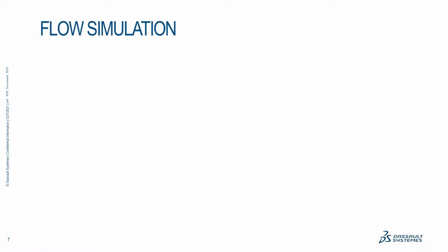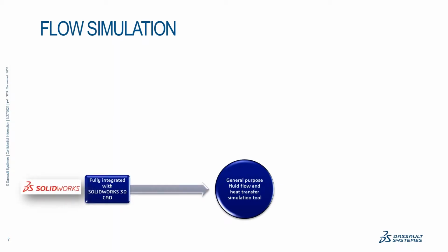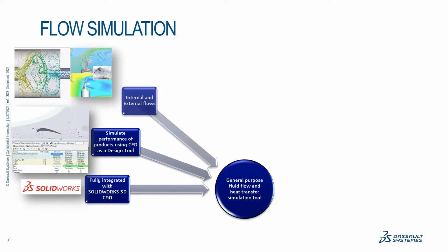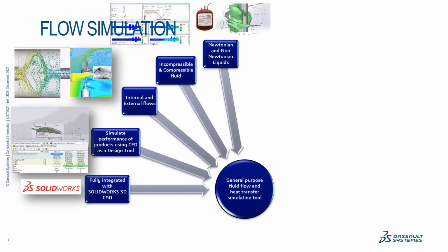Now, Flow Simulation itself is a general purpose fluid flow and heat transfer simulation solution. The biggest advantage of it is the seamless integration within the SolidWorks CAD environment. It is a design tool for mainstream applications, extremely easy to use. It has many capabilities, capturing internal and external flows, incompressible and compressible fluids, Newtonian and non-Newtonian. Non-Newtonian, for example, comes in very handy in some applications in the life sciences.